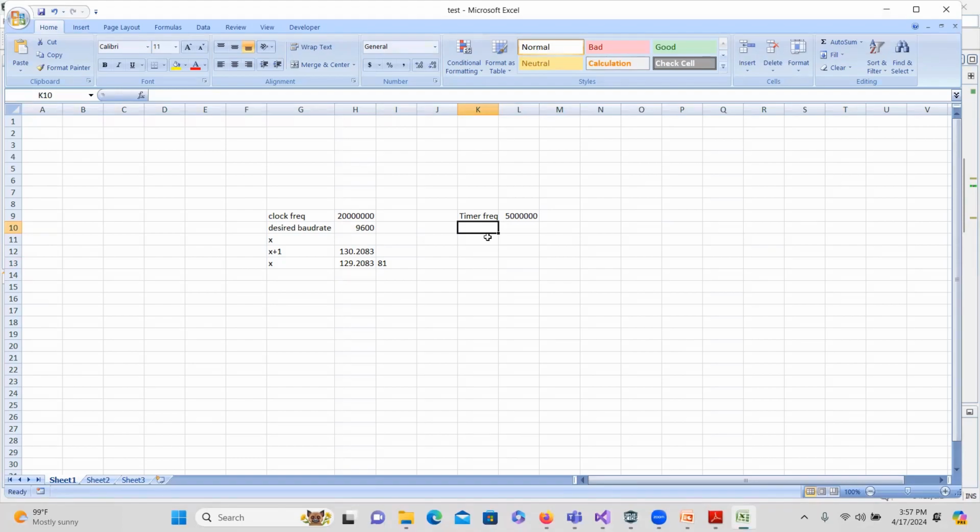So then we have to find out the tick. There is something called the prescale. This prescale means you can further divide the clock. If I set that value to 1, then one tick means the time the timer takes to make a single count up.